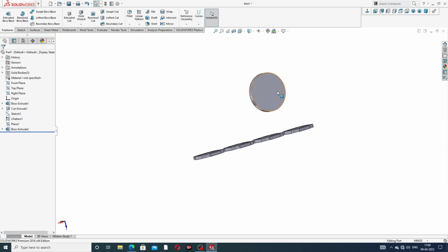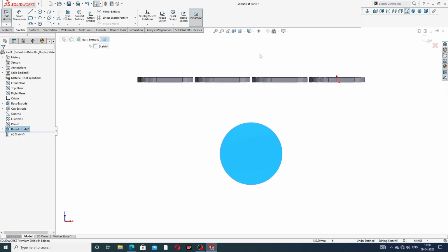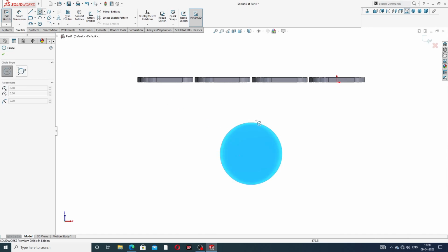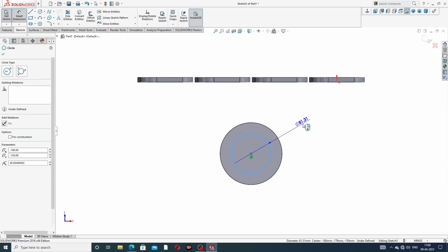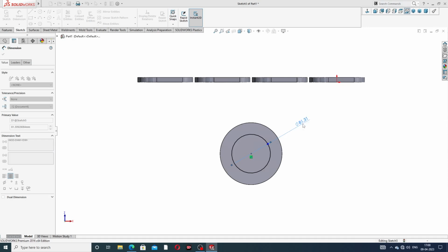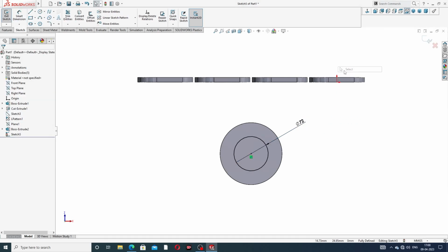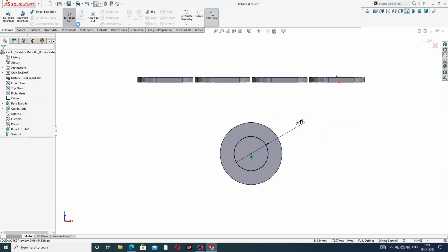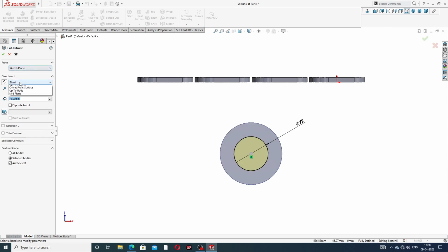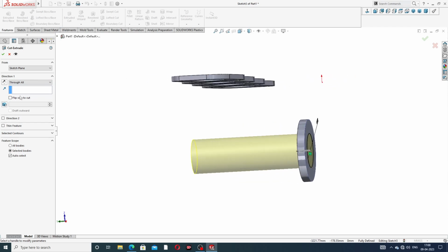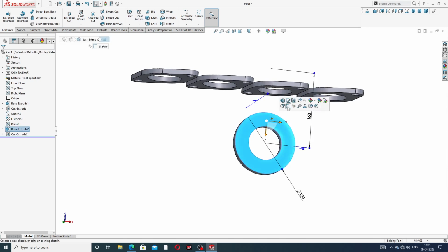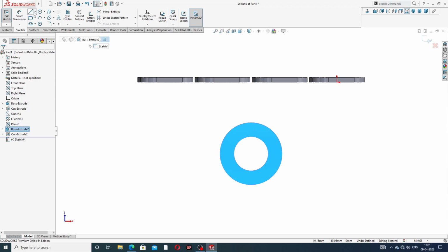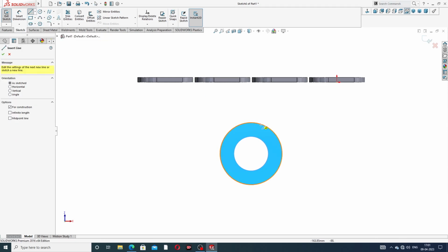Okay, and also this Sketch Normal, and drawing a circle is this, and this circle is cut out, and use 72 millimeter cut out is perfect, and use Extrude Cut, use Through All, and click OK.